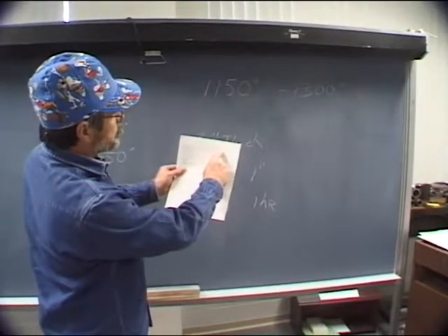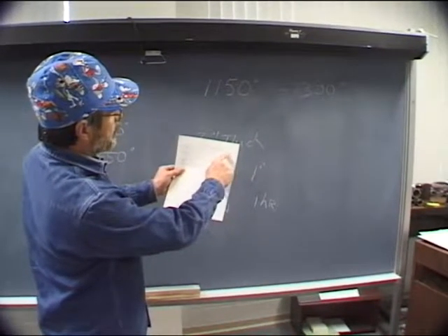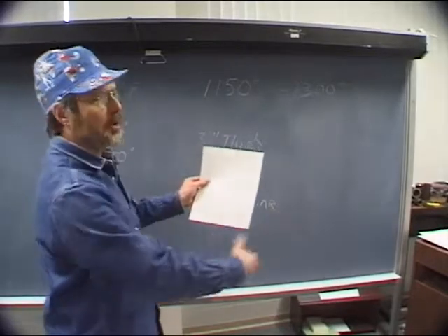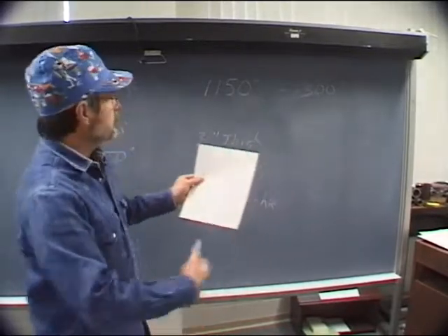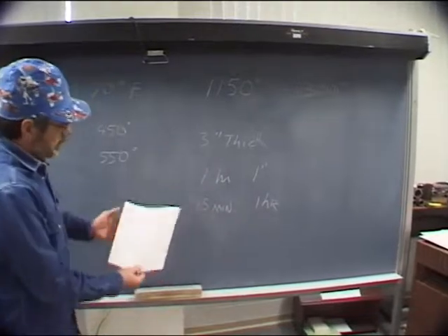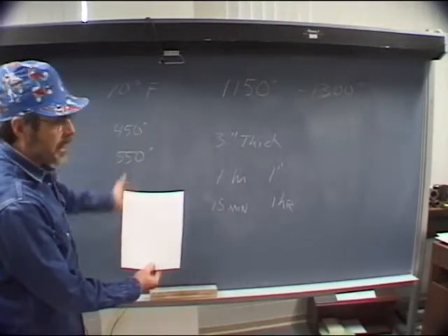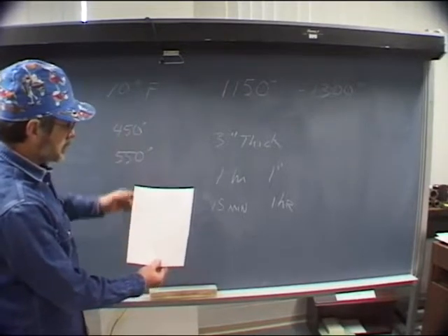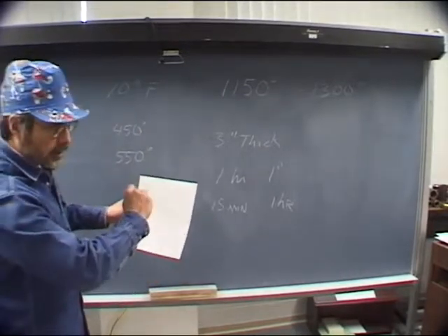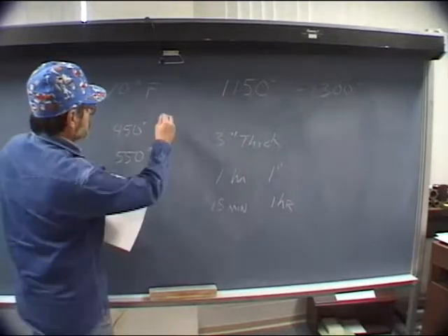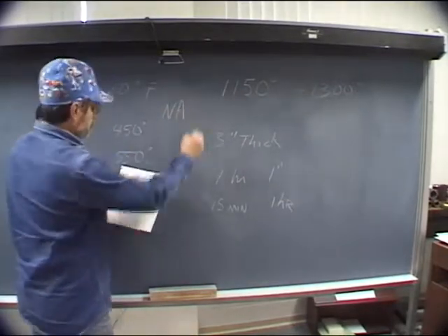You'll notice it says temperature range, what you're going to have it at, and time range, how long you're going to do it, how long you're going to soak it. It's called soaking. Okay, gases, QW 408. Again, that's not applicable to the procedure we've written, so you can leave that blank or put down not applicable, NA. Usually that's how it's written, NA, not applicable.